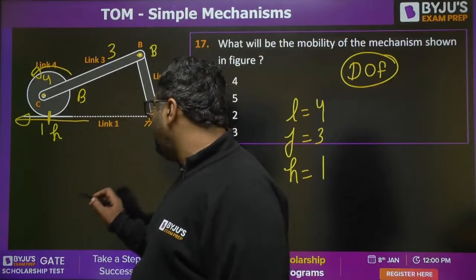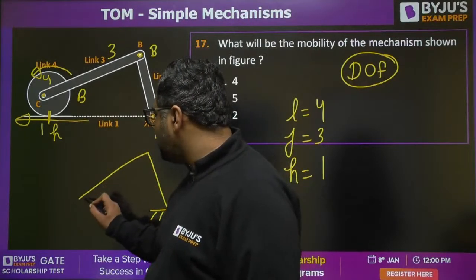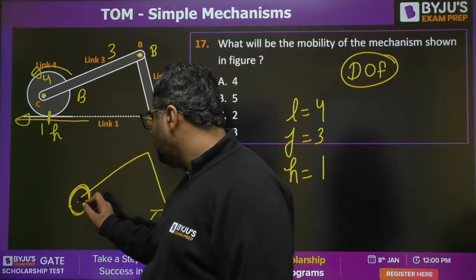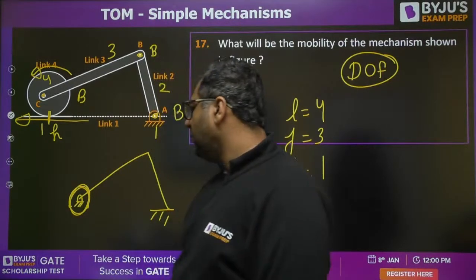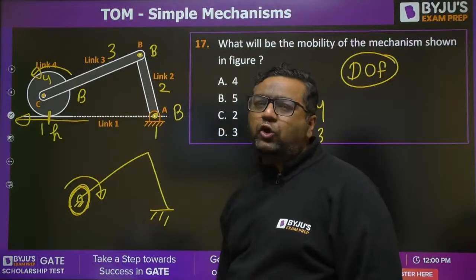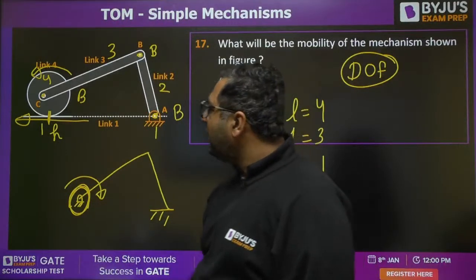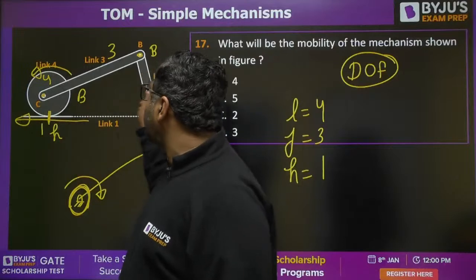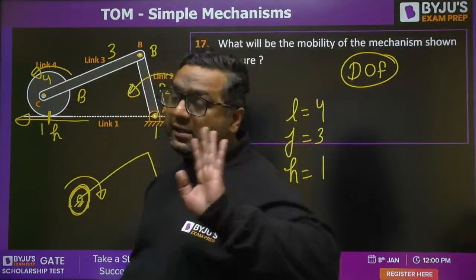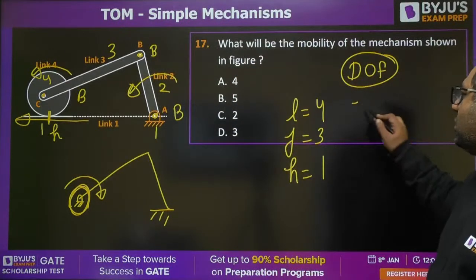Okay, if we would be having the connection in this way, just imagine if this connection would be like this. Means if the motion of this roller is pure rotation, not pure rolling, then the motion of this would be a redundant motion. But here if it would be moving in this way, obviously your entire mechanism will run. So this motion is not redundant, it is a part of mechanism. So you will be saying there is no redundant motion.